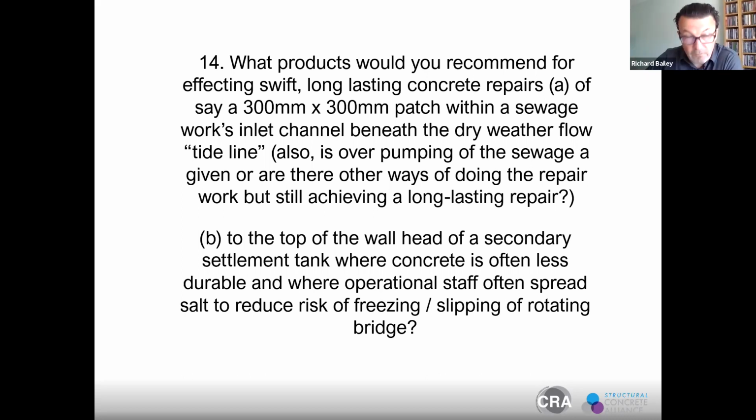I'm guessing with the nature of the question, when you talk about floor joints, we are talking about an industrial or warehouse type environment. One thing to think about is the stability of the actual slabs. We've undertaken a lot of work in the past to not just repair the arises around a warehouse floor joint and then the joint itself, but also to fill any voids that might exist underneath.